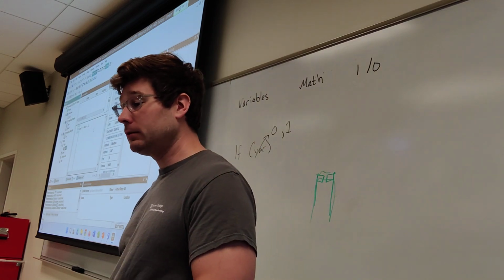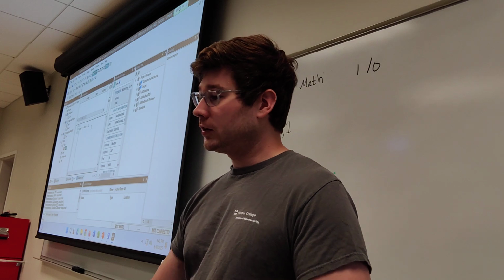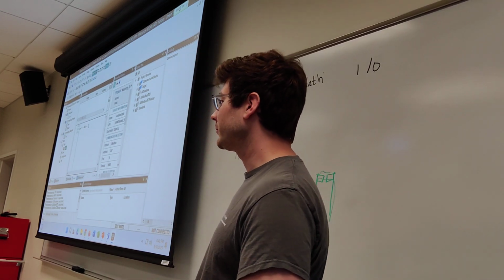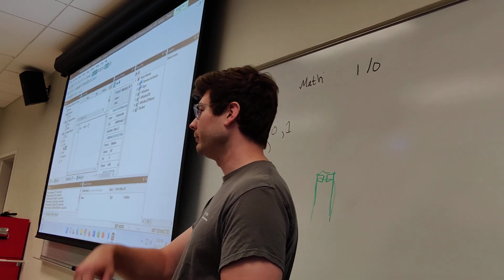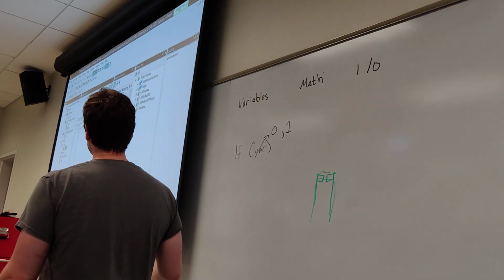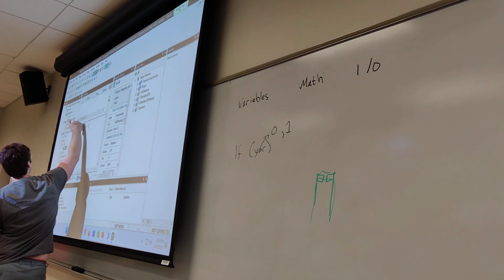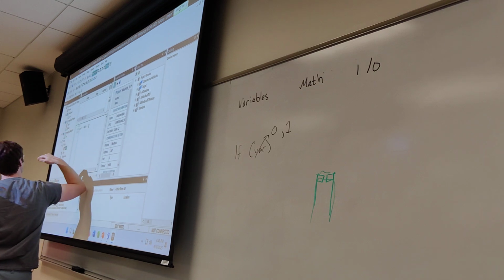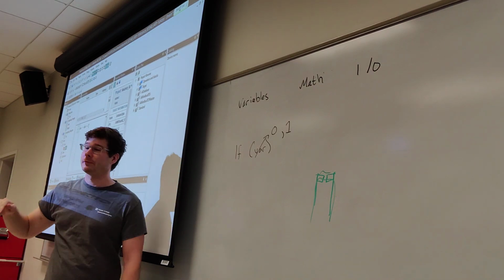That means every 10 milliseconds, roughly 100 times a second, we take the variable count and set it equal to itself plus 1, okay? And then 10 milliseconds goes by, and then we do it again. 10 milliseconds goes by, and we do it again, okay? So that's essentially how this works. So it will run line 1, there's nothing on there. 2, it'll do it. 3, there's nothing on there. And then it'll do it over again, and over and over.